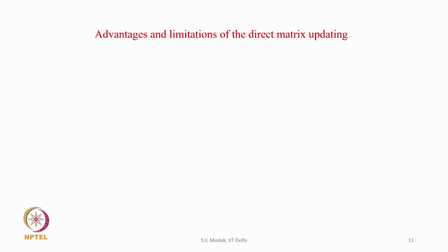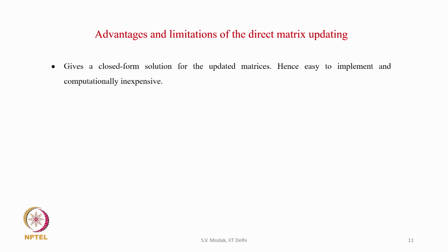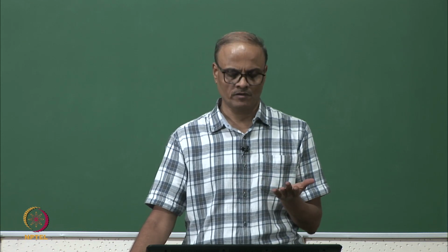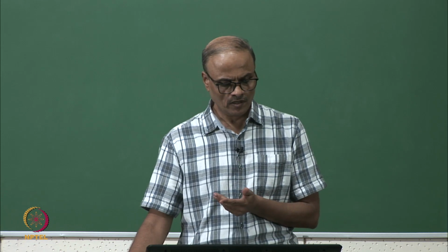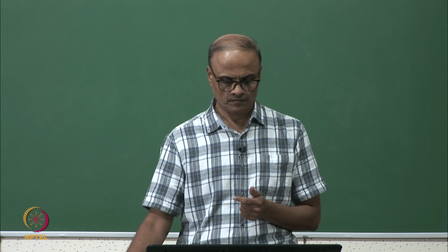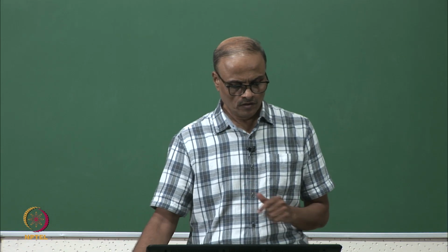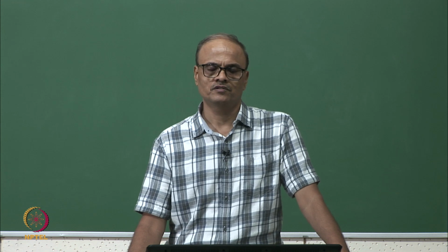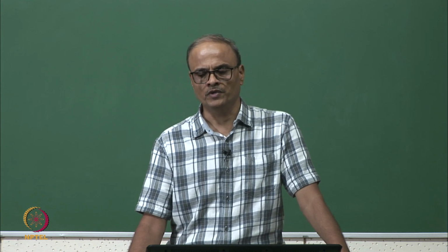So, let us now look at the advantages and limitations of direct matrix updating. It gives a closed form solution for the updated matrices, because we saw that the updated matrices were in the form of a matrix equation. We just have to compute that equation to find the updated matrices. So, it is easy to implement and computationally inexpensive. Direct matrix updating is a one-step procedure, it is not iterative, and so there are no issues of convergence which may be faced in iterative methods.